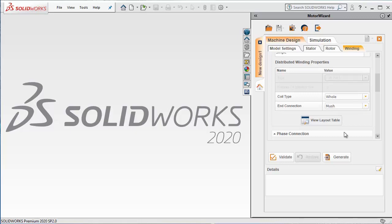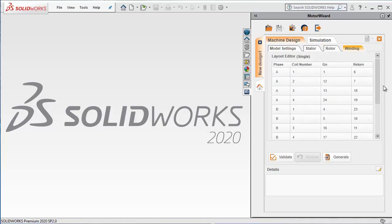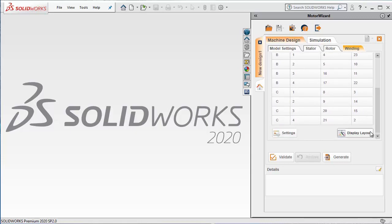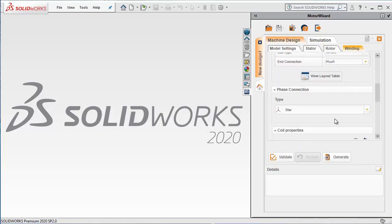To view the winding layout, I will click on View Layout Table. You will see that the layout editor is automatically filled for the three phases, which are phase A, phase B, and also phase C. You can also view the layout by clicking on Display Layout, or just go back to the settings. The phases are star connected.